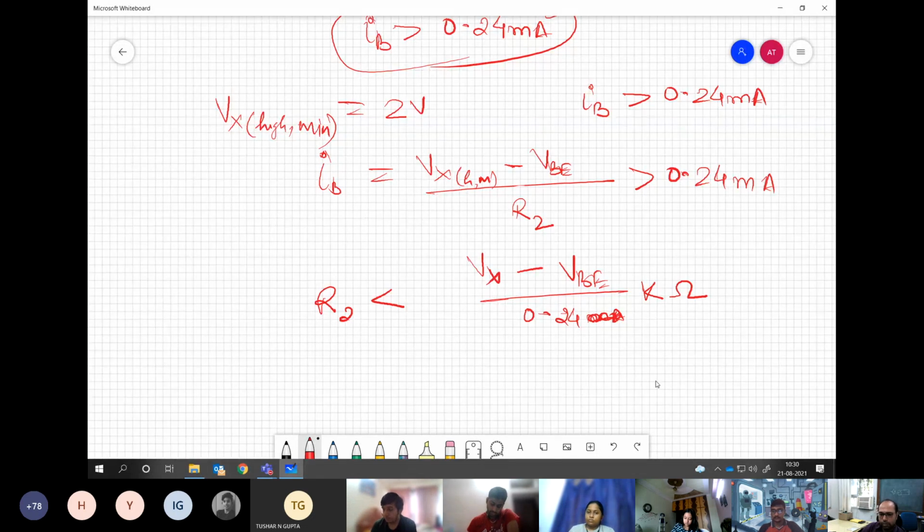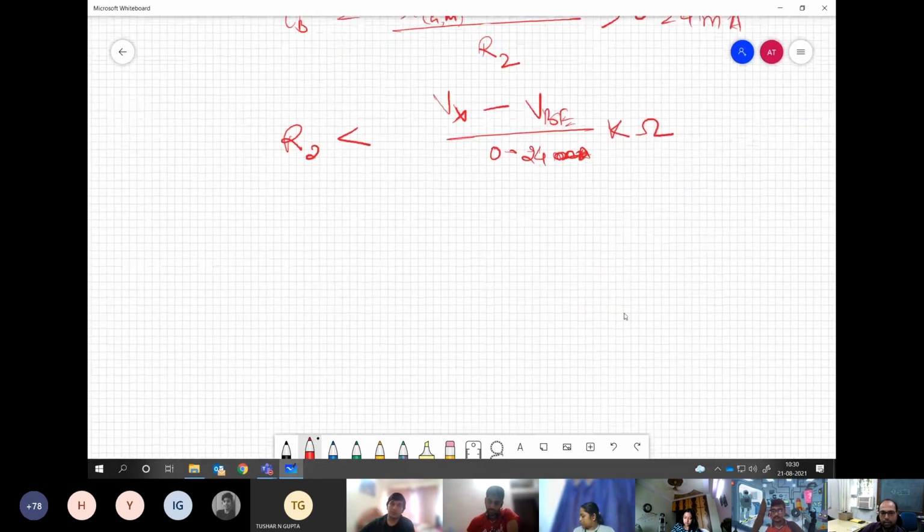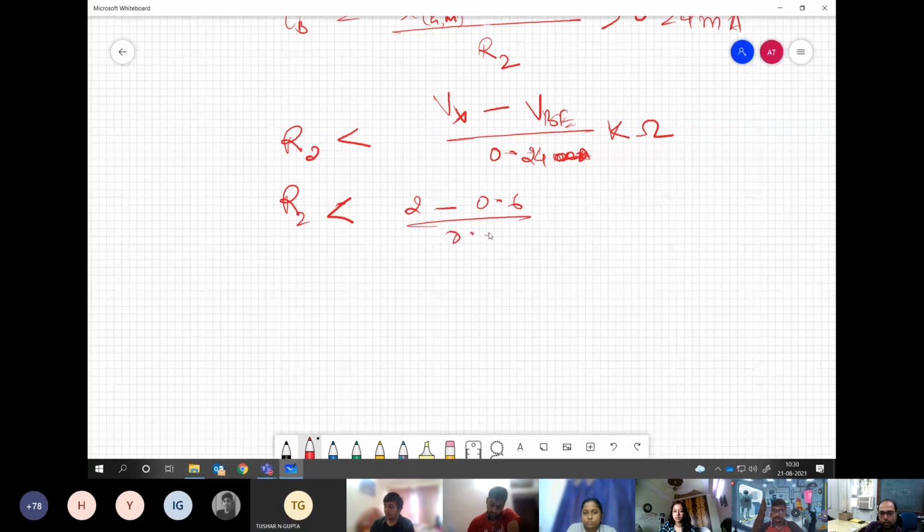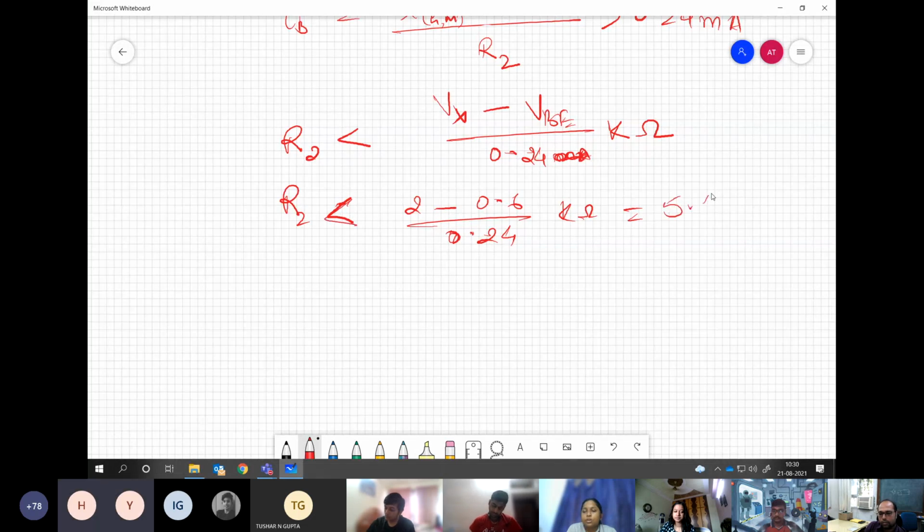Understanding my point? Now what are the numbers? Vx is how much? 2 volts. 2 minus 0.6 divided by 0.24. This is in kilo ohm. Now what is this number? 5.83. So your resistance must be less than this number.